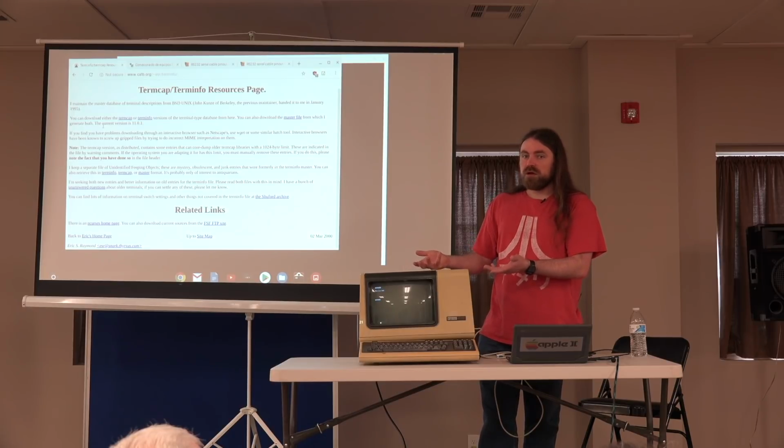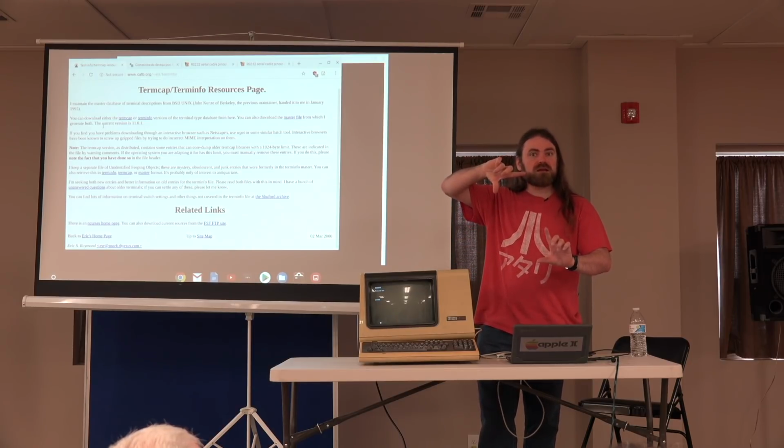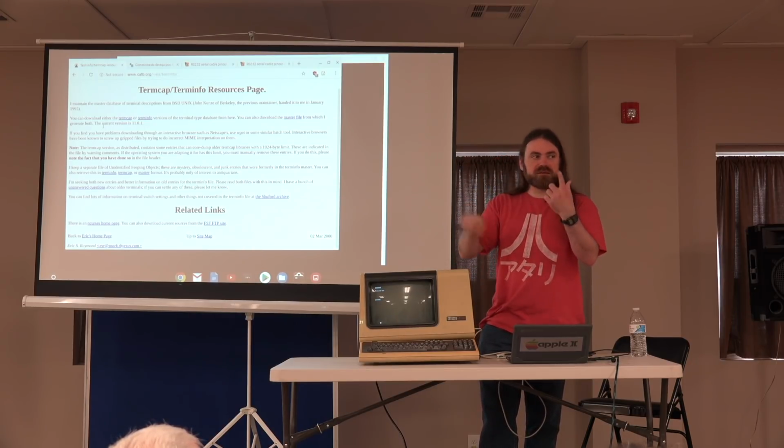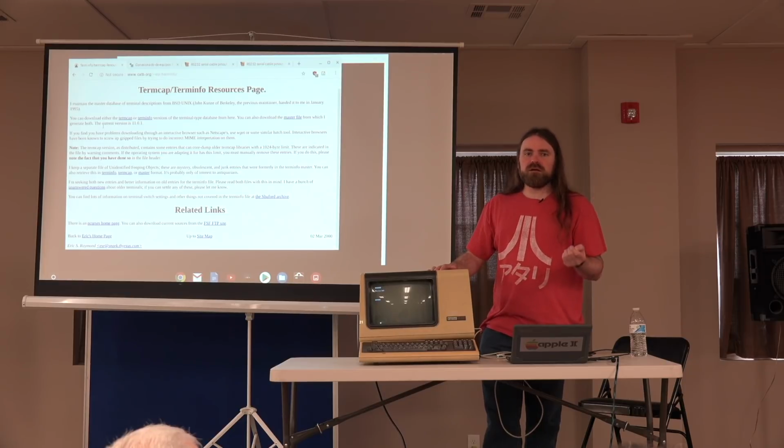Usually it's static memory. Some of the really early tech I was talking about earlier uses shift registers. There's a board about that big full of metal can shift registers that just sits there recycling the data around and around, because RAM wasn't really an option. Some really early terminals, like some of the Hazeltine terminals, used core memory to store that information. There were little bitty core planes in there.